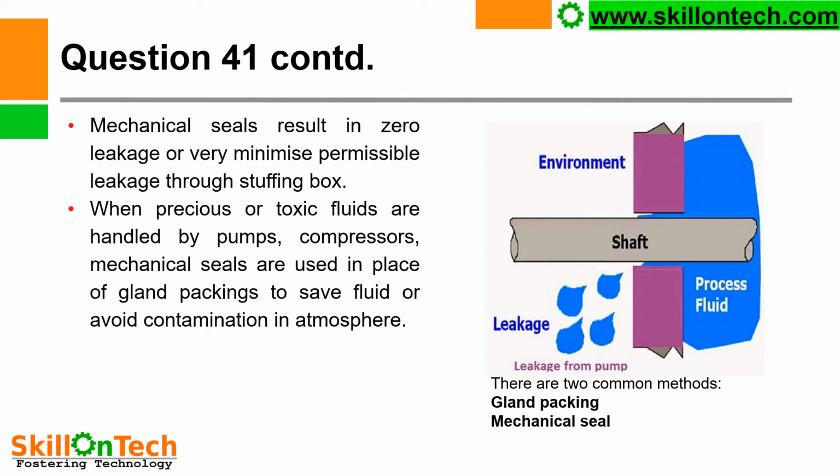When precious or toxic fluids are handled by pumps or compressors, mechanical seals are used in place of gland packing to save fluid or avoid contamination in the atmosphere. Because if you are handling a precious liquid, then wastage of liquid may be uneconomical.